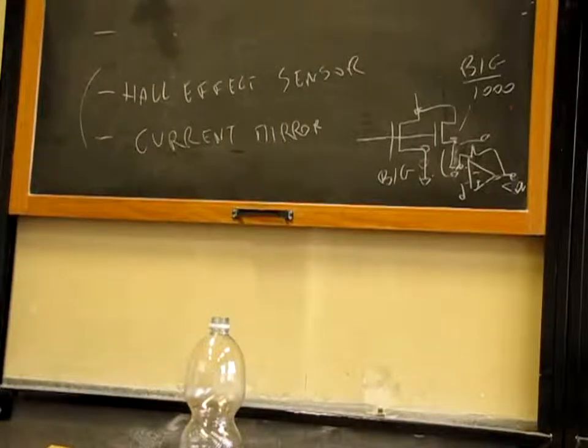Unfortunately, and this is the problem, the current transformer cannot work with DC. If you have a DC current, it's not transferred to the secondary winding. If you add another winding on your inductor, you get the ripple. That's okay, but not the DC value. But a transformer is the right solution if you can do something about it.